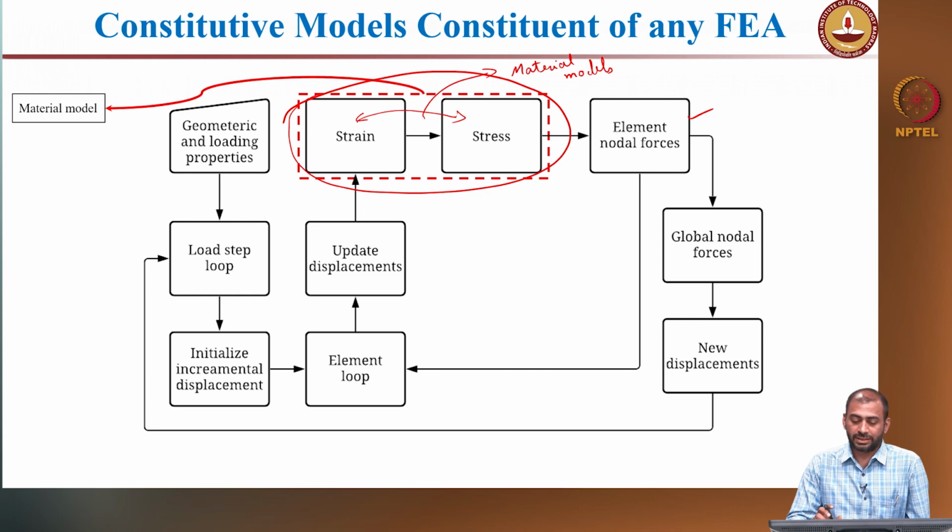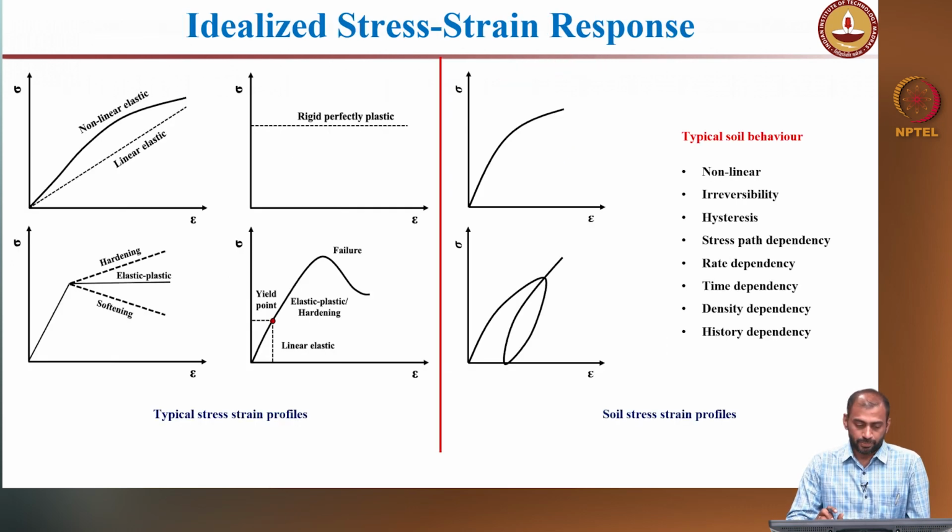So, we have to be very careful in choosing an appropriate constitutive model for the geomaterials, and especially what we are looking for. If you are looking for large strain problems, you need to choose a model which predicts the large strain response accurately. So, depending upon the problem, depending upon the material, you have to choose an appropriate constitutive model.